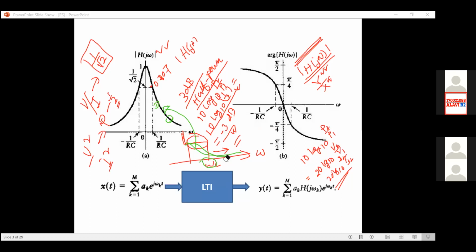So the most generalized definition of obtaining the cutoff frequency is this one: if power is going to half, then beyond that frequency, we will not consider the output as reasonable. So that frequency can be considered as your cutoff frequency or half power point frequency in terms of power. But if it is in terms of voltage and current, it is the point where your voltage amplitude or current amplitude is going down to 70.7% of your maximum value.